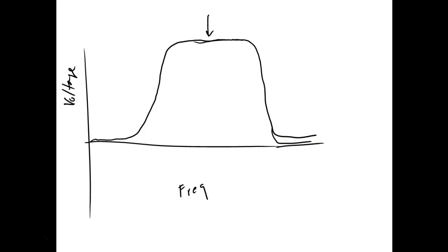Okay. And what we do is we say, okay, this would be my V out max right here. And then somewhere along this line, we set a bandwidth, and we call this F1, and the upper limit we call F2. So we measure bandwidth by saying F2 minus F1. That's the way we measure bandwidth. But what would half power be relative to voltage?